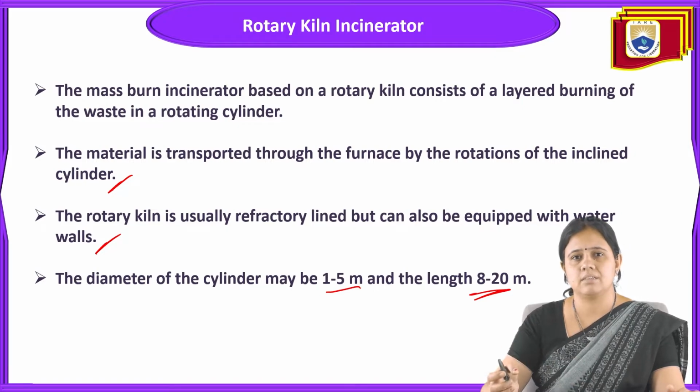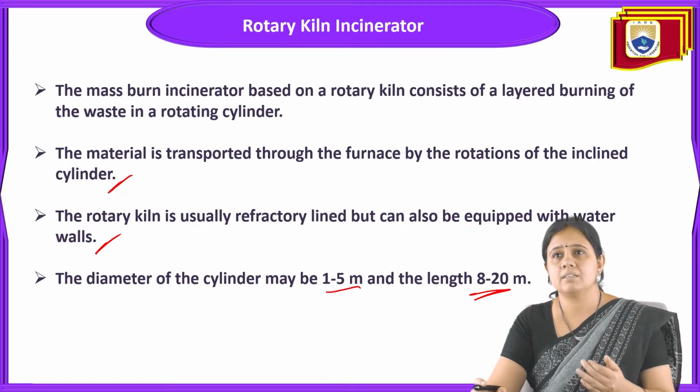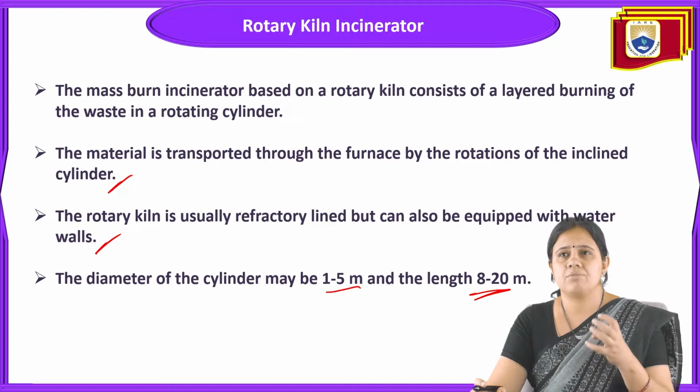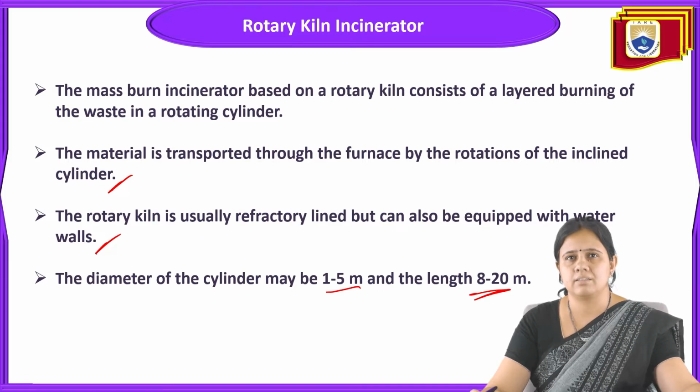It is again an incinerator. The only difference is that it consists of layered burning of the waste in a rotating cylinder. Inside this cylinder-shaped chamber, the material is transported to the furnace by the rotation of the inclined cylinder.